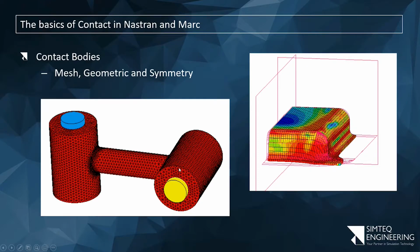So I've got all three of those in this model. In this case, this is a mesh, a single body. Then I've got a rigid body over there and a rigid body there. Those are the geometric ones. In other words, it's a surface. They've closed it with caps, possibly. Don't really need it, to be honest. But in theory, I could have used either just one, or I could have used three faces. In other words, the cylindrical and the two circular faces. Another contact body over there. Now, this kind of model will allow me, if that wasn't there, to rotate about this, and this one to rotate about that section over there.